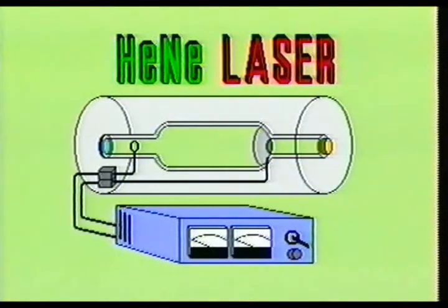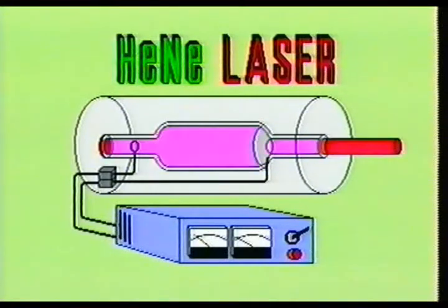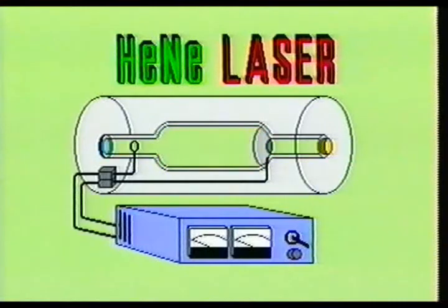When the laser is first activated or turned on, the HeNe tube receives an initial ignition pulse of 10,000 volts, which breaks down the gas molecules and starts the laser operation. When the gas becomes ionized, the HeNe tube will conduct a current flow of only a few milliamperes and maintain a voltage of 1,000 to 2,000 volts. The electrons in this discharge path will raise both the helium and the neon atoms to their excited states.